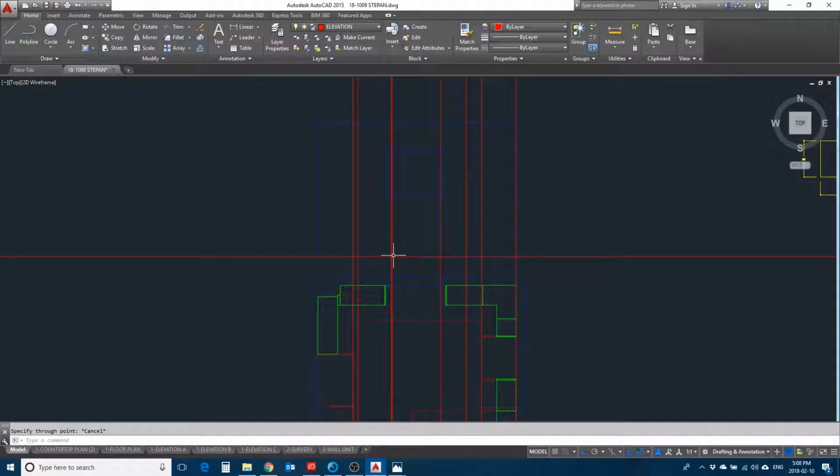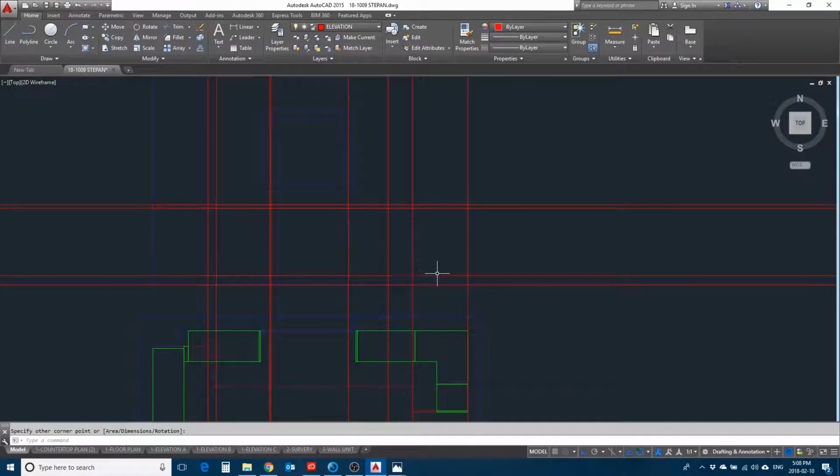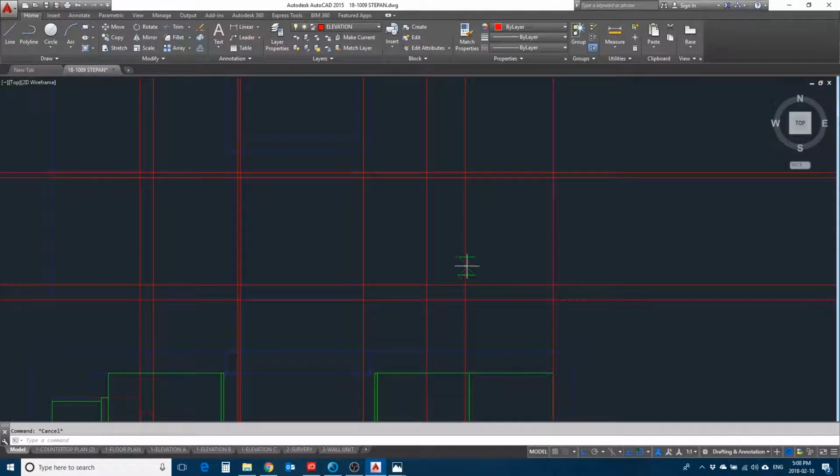So we know the kick is 4.25, offset 34.5 is my total height, offset 1.5 is the countertop, and those are industry standards pretty much. So we have the corner cabinet, full door, offset 6.25, that's our top drawer, and a door, rectangle.